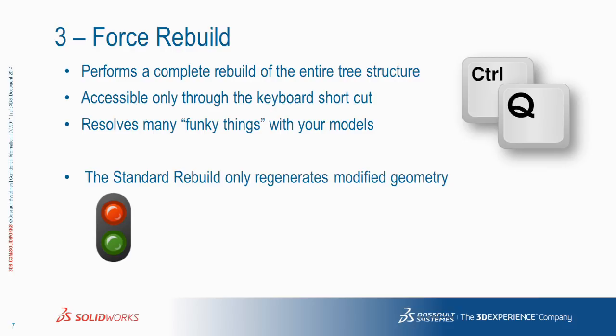Right? Force rebuild. This is one that I want you guys to file away and remember that it's there and use it. And why it's beneficial is because it helps you with some geometry or models that might have some funky things going on. All right? It's a little bit different than the regular rebuild in that it rebuilds everything from start to finish, all of the geometry. The regular rebuild will just rebuild what's flagged, the geometry that's been modified or changed. Right? So this is what we really keep in our back pocket to try to fix a model that might be a little funky or something.